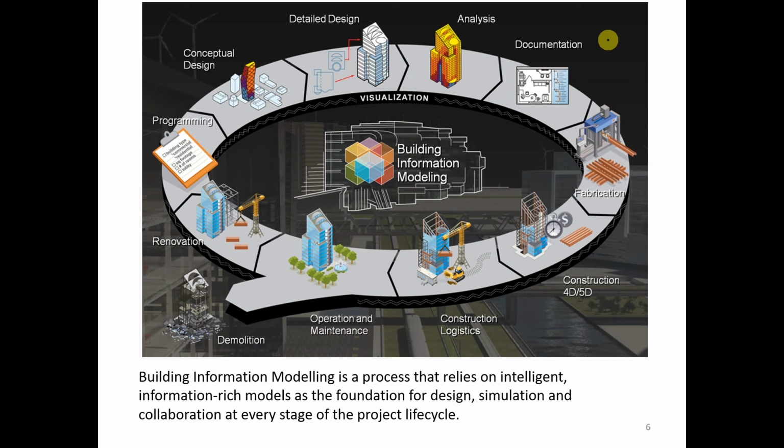So that's the essence of BIM. So that's working with the 3D models in that respect. Now the thing is that the model itself is the heart of the BIM process. So it starts off here at conceptual design. Now when you're using Revit, you don't have to start off by drawing walls and putting in doors and windows. You can start off with primitive shapes as a conceptual design. So you can actually put your building together with shapes.